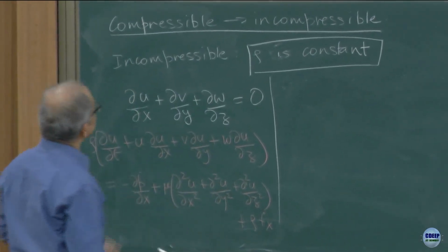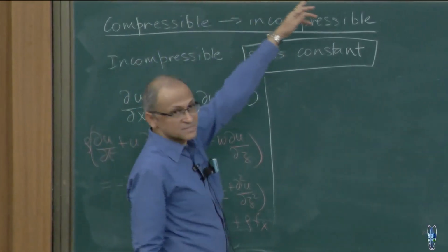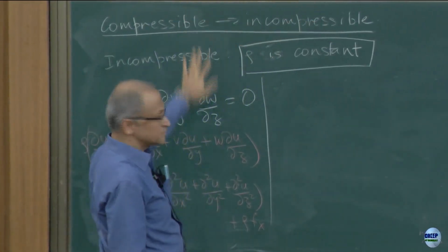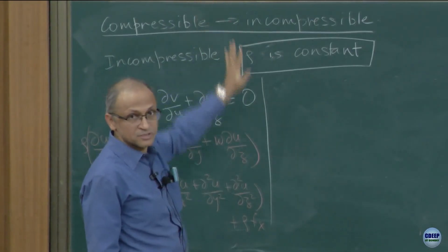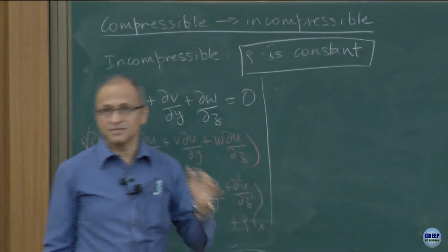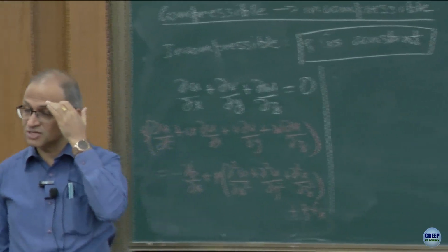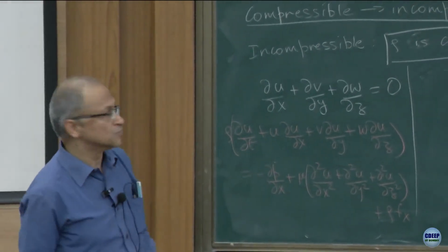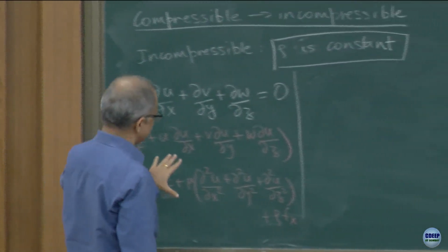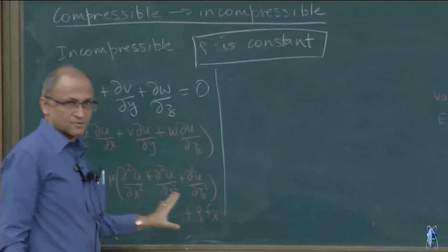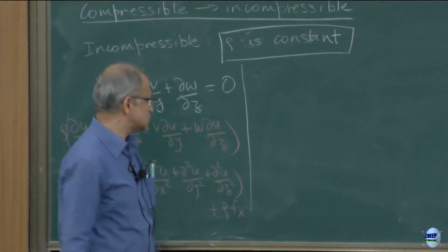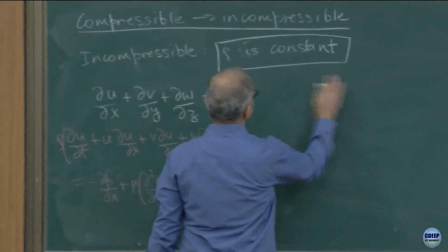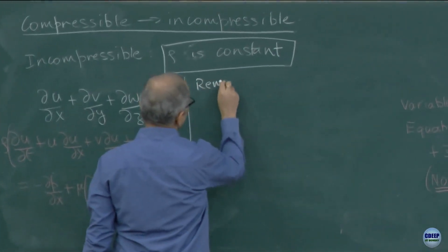The first thing, as we had said, is that the right-hand side of the Navier-Stokes equation is different in the 2 scenarios, compressible and incompressible. The left-hand side is exactly the same. There is a substantial change in the continuity equation, which of course allows us to get to a simplified form as shown here. That's the first remark. So we are making a few remarks about the equation.